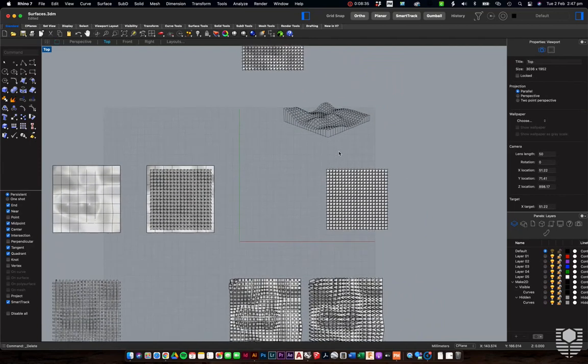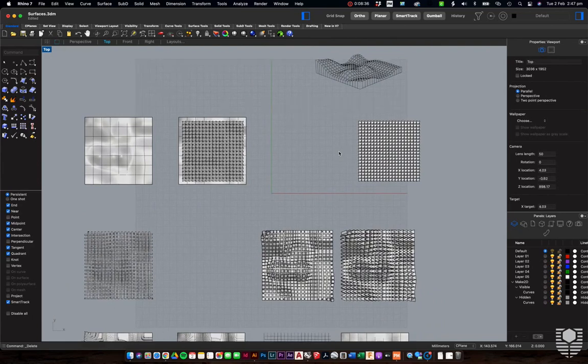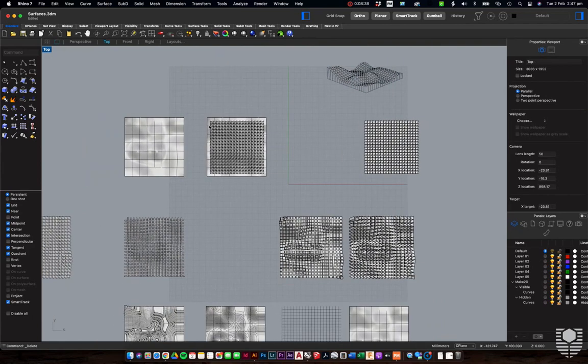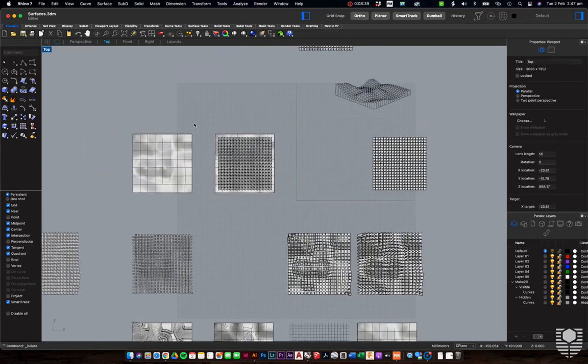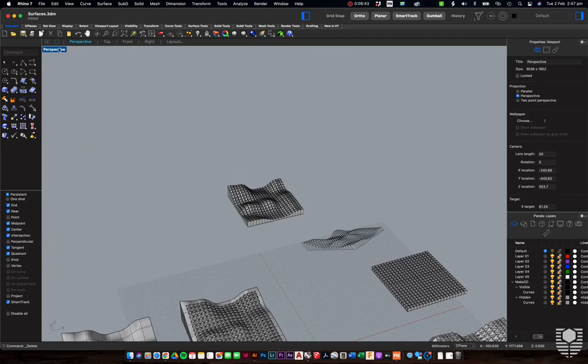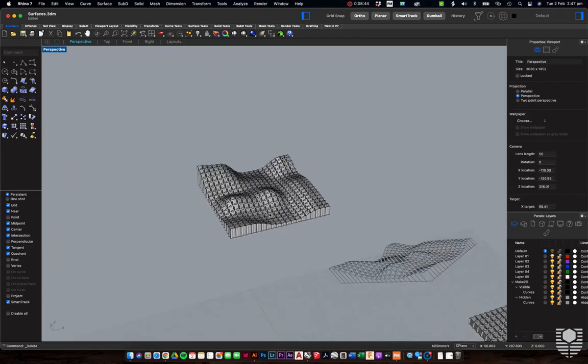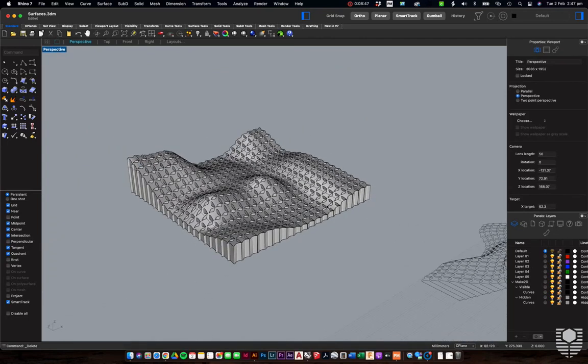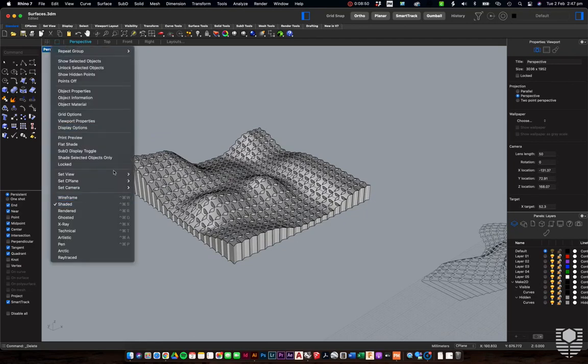Now, something that we particularly like to use for our architectural visualization is, of course, the axonometric. So in order to construct an axonometric, you will need to change one of your viewpoints. So let's say we're currently in perspective, and I really like that perspective, but I also need a proper axonometric, a scale view.